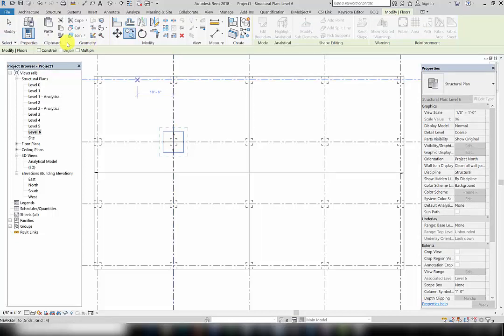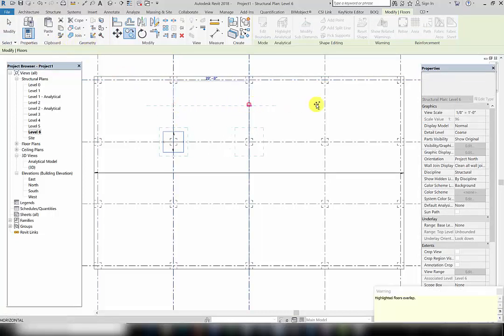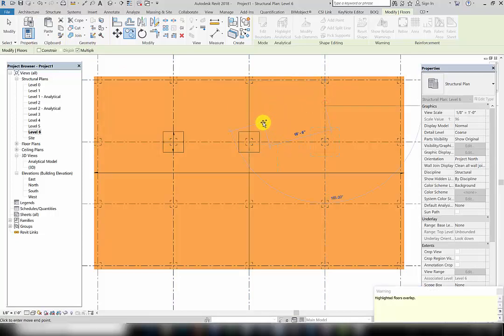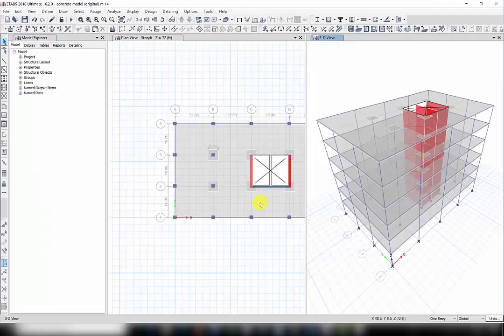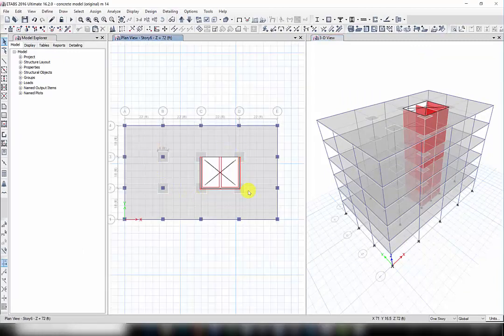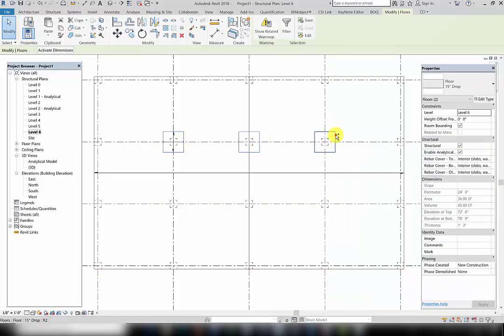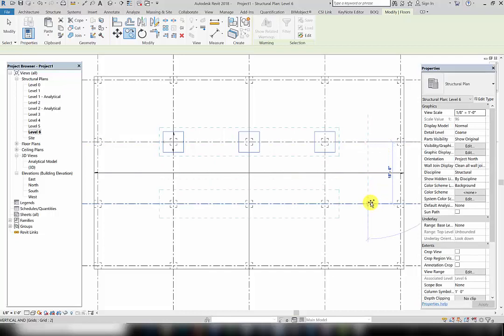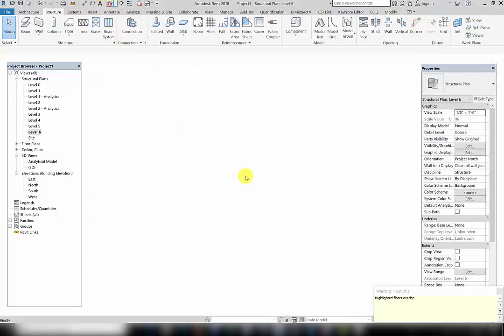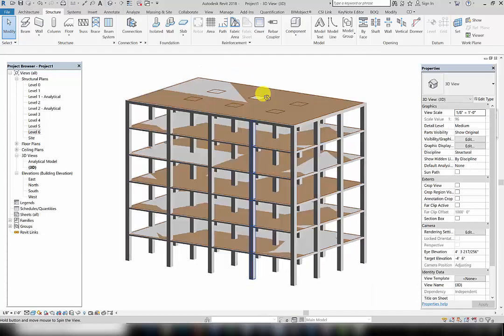Then I'm going to copy these multiple times on the grid. As you can see, we have only 6 drop panels. We don't have them on the periphery. Instead, we have the marginal beams, which we are going to model in the next step. So we just take these and copy them from here to here, and look at it in 3D.